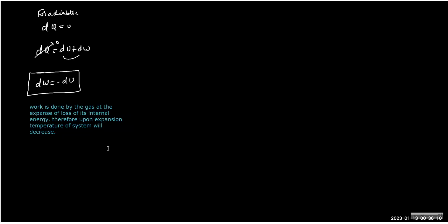So can we say because of this particular region, upon expansion, the temperature will fall down? Because internal energy is defined by temperature. So less energy means less temperature. Yes or no? Yes, sir. So you all realize that the gas will cool down.